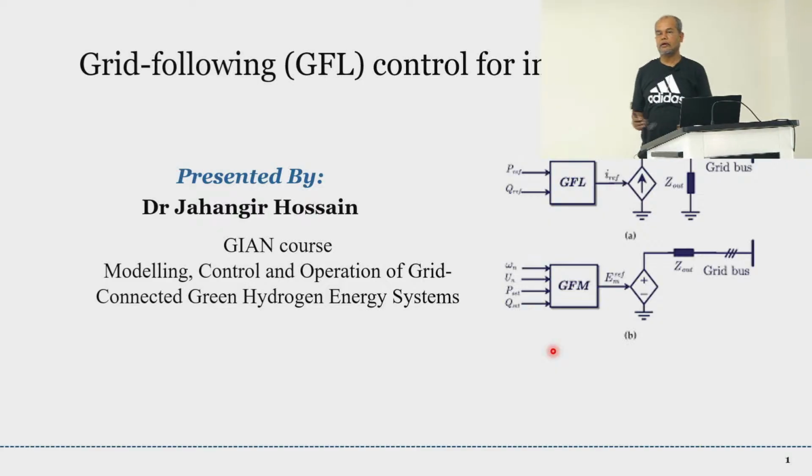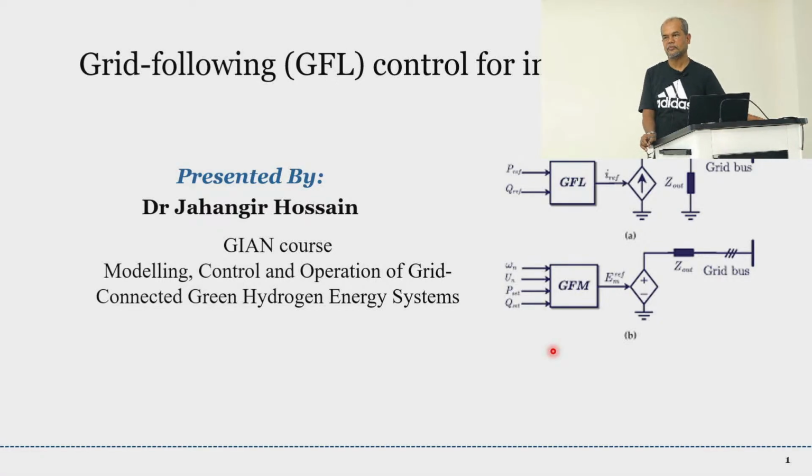So again, if you remember what we discussed before, which needs an inverter, the electrolyzer or the fuel cell? For the fuel cell, right? Because the fuel cell produces DC power and then we convert it from DC to AC. But for the electrolyzer we need DC input, right?